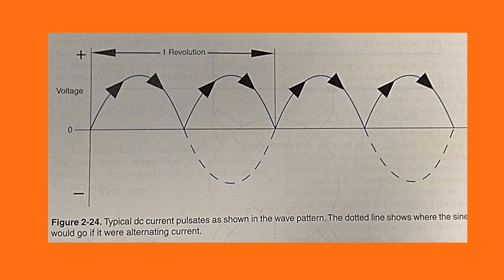Power plants generate three-phase power because it is more efficient. The electric power is converted to single-phase for residential use. Three-phase power is supplied to commercial and industrial customers for either of the following reasons. Three-phase power is necessary for high-demand applications and cost-effective where there are many motors. Three-phase motors are simpler, less expensive, and more powerful than single-phase motors.